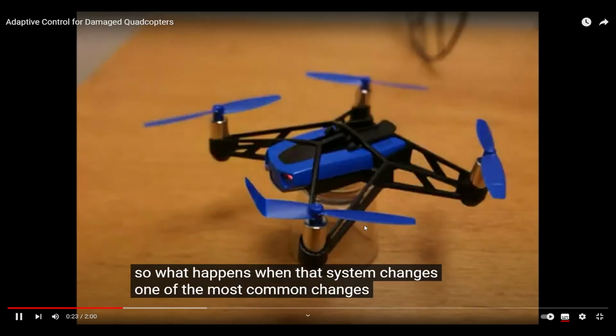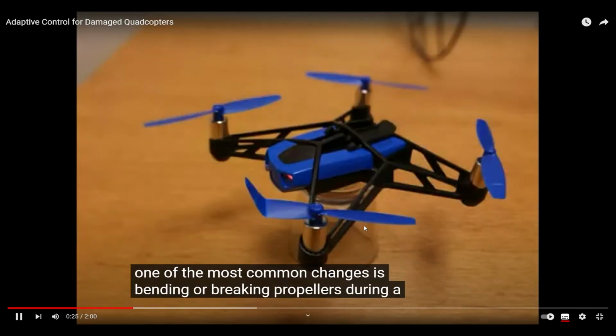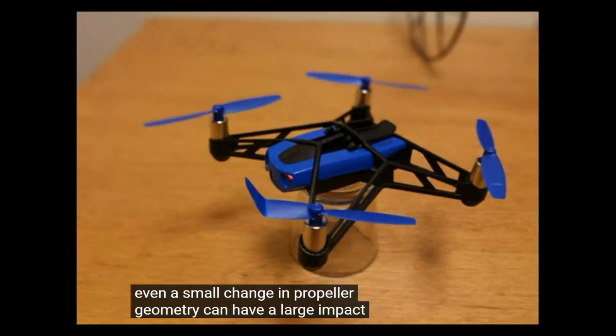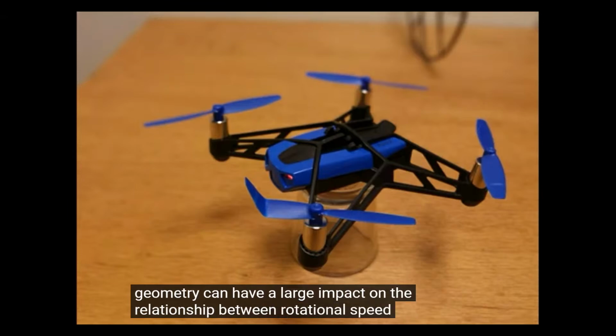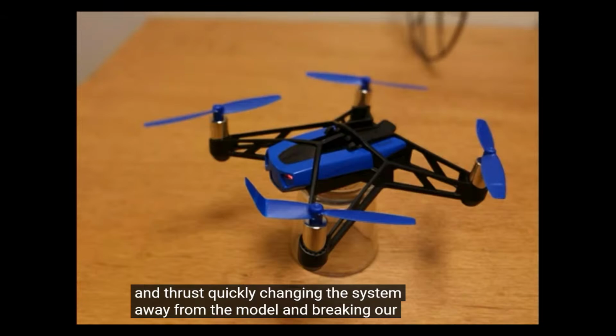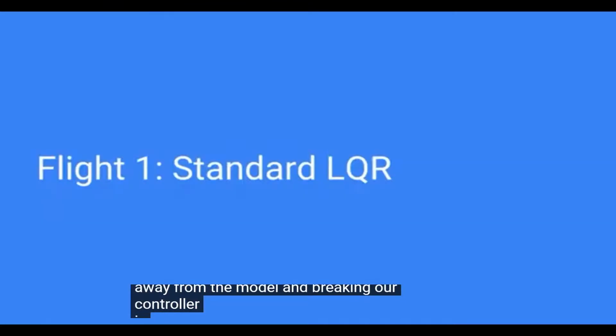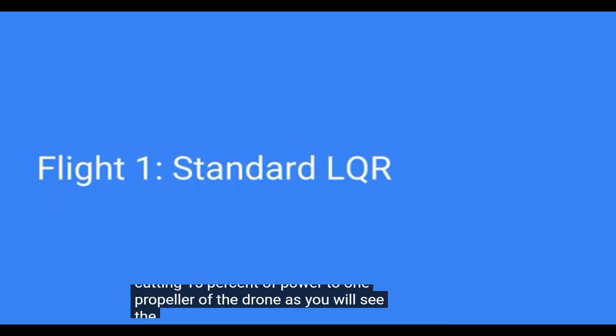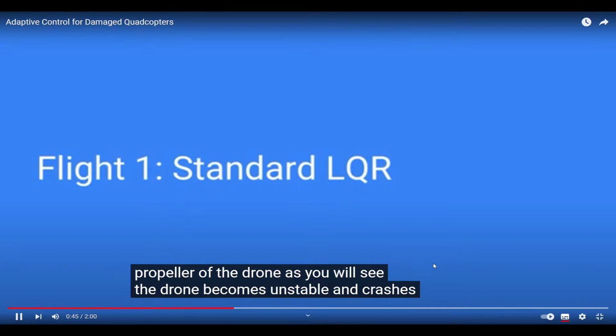One of the most common changes is bending or breaking propellers during a crash. Even a small change in propeller geometry can have a large impact on the relationship between rotational speed and thrust, quickly changing the system away from the model and breaking our controller. In this flight, we simulate damage by cutting 15% of power to one propeller of the drone. As you will see, the drone becomes unstable and crashes.